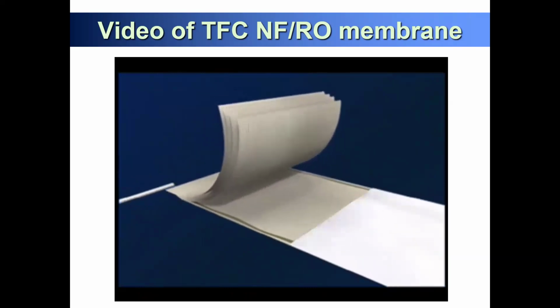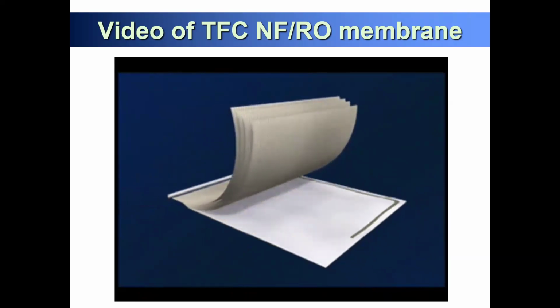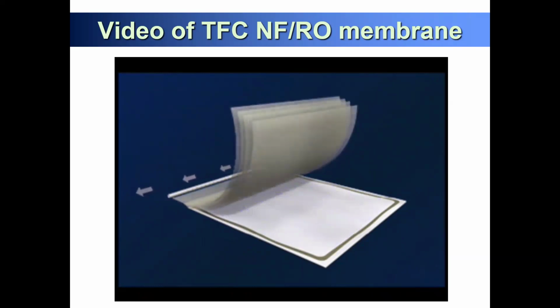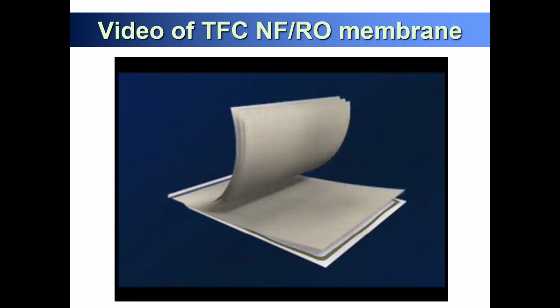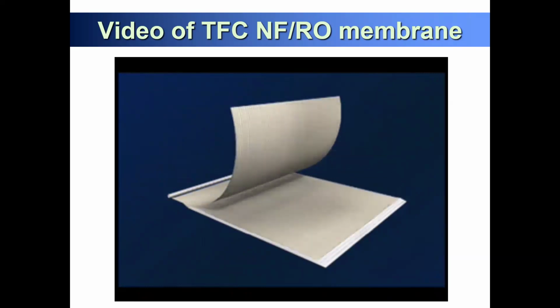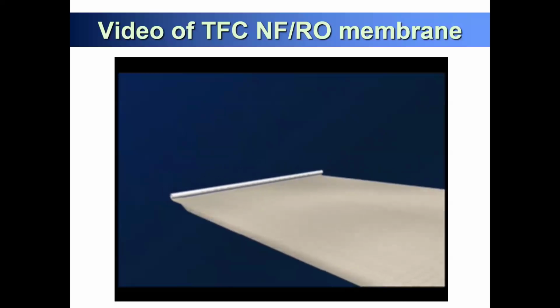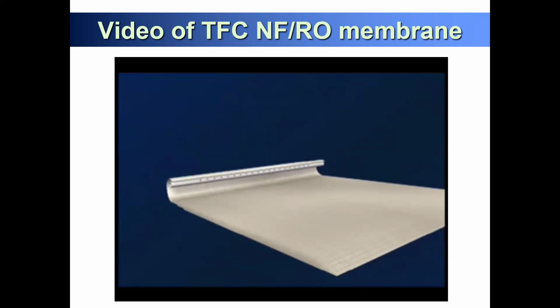membrane surface. The leaves of membrane and feed channel spacer are then combined with a sheet of permeate spacer, which provides open flow channels that will permeate even under high pressure. The leaves are glued along each of the three exposed sides and then rolled around the core tube.